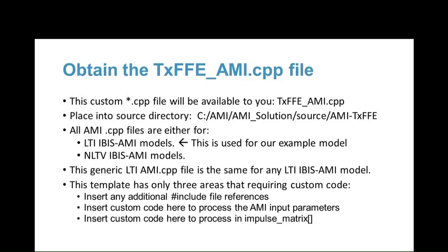Then you'll obtain the C++ file at the link I'll be showing you, and you place it in the directory for the TXFFE. Again, the templates can be either for an LTI model or for an NLTV model. It's LTI for our example. And so this generic LTI AMI CPP file is the same for any LTI IBIS AMI model.